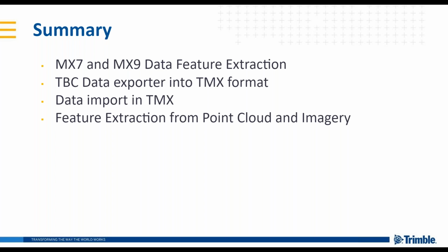Do we need to classify ground while extracting features? No, and even if you classify ground in TBC, the classification is kept in the LAS files. However, TMX will not read the classification. It's a feature on the list of improvements, but for now, TMX does not work on any classified point cloud. So it will be imported without any classification, without any regions. It will be understood as just one class.